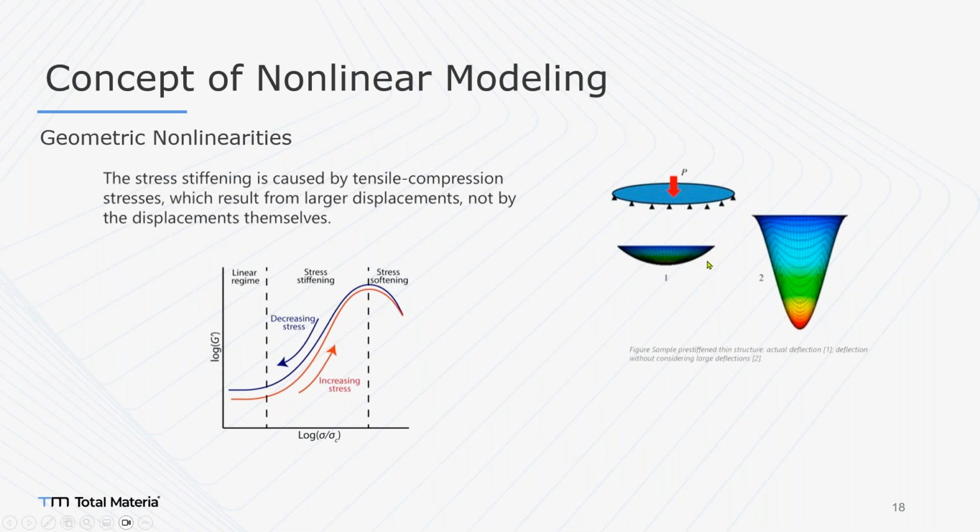That's why if we go for the linear analysis, in some examples we can get much more displacement. So we need to avoid it. But in some cases, it could be the opposite. Sometimes if you turn on the nonlinear geometry, you can get much more displacement on your geometry actually.